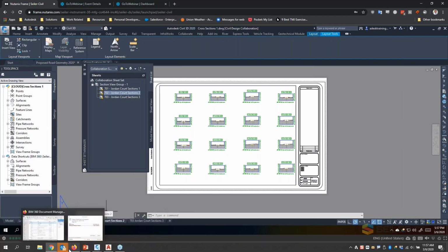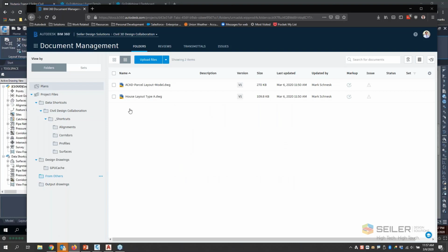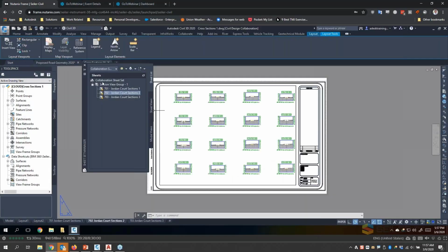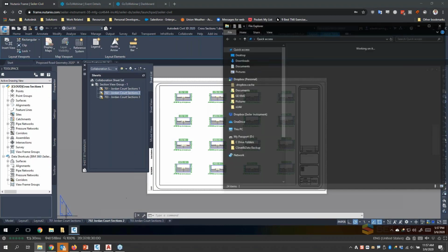One final recommendation I have for you. So when you publish, in the end here, one of the things we do with collaboration is publish those extra plan sets. My recommendation is you do not publish the drawings to the plan area. Go about your normal publishing of file sets using the plot and publish tool, and then go ahead and copy the PDFs up to the plan areas.